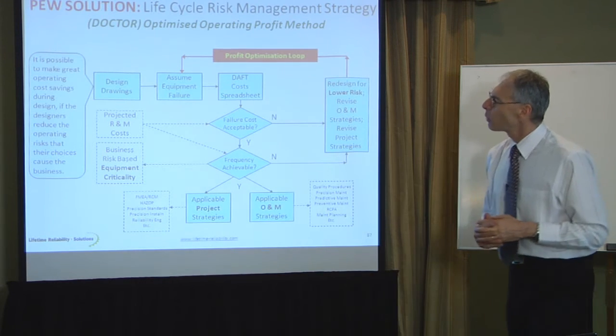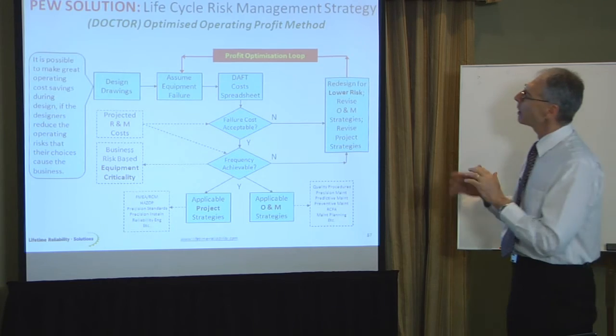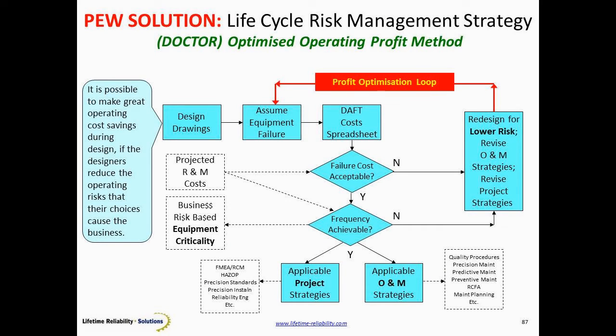In plant wellness, we have a technique to intentionally ask the hard questions in the design phase. While the design is still at a drawing level, we say, look, here's the machine, here's the layout, here's the assembly drawing. What if that part fails? What's the cost of this bearing failure in the future? And we can price the cost of failure.